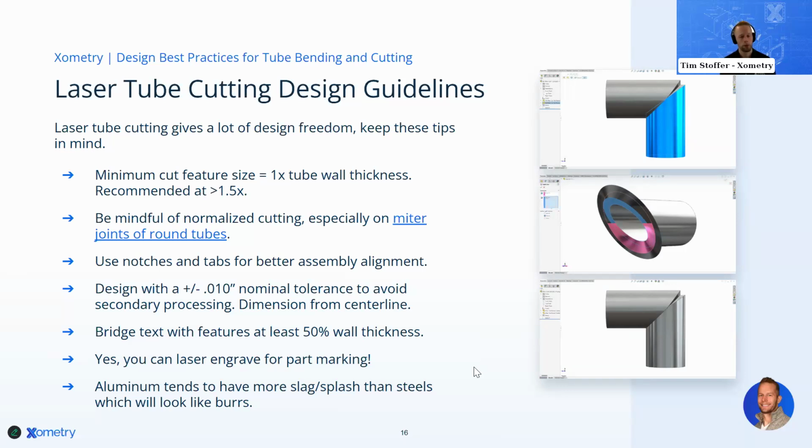More helpful tips that you want to incorporate when you're designing is the indication feature. So you can cut notches into your tube shapes. So when you're putting things together, you have an indication. It shows you where this part goes. Looks like Greg might have an example there. Yeah. There you go. This is basically free.